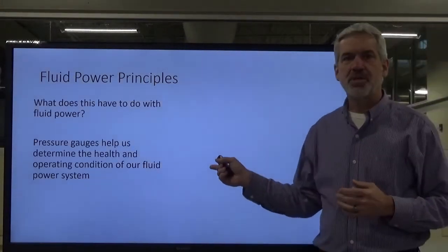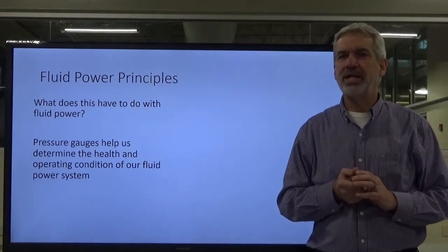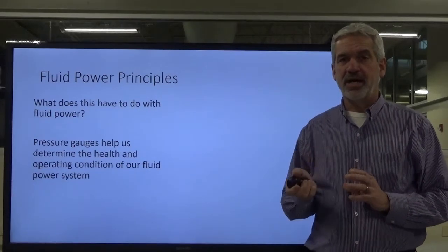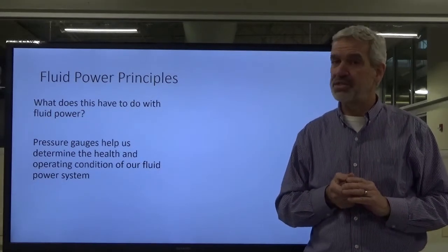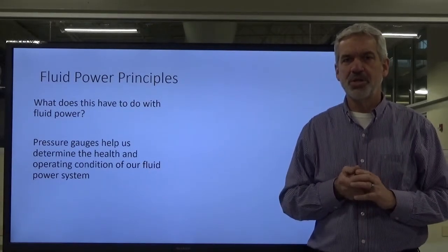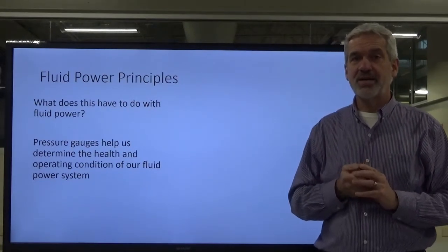And again, this helps us as far as troubleshooting and knowing what we are actually reading, because vacuum plays in inches of mercury, which is a negative pressure, but it's still considered a pressure. That all comes into play when it's time to troubleshoot, which we'll get into in some of the additional classes. But for right now, that's going to take care of things.